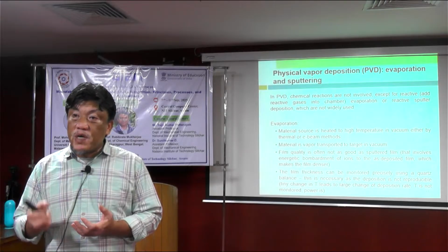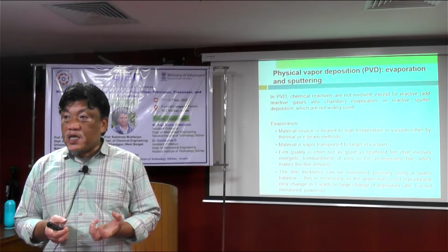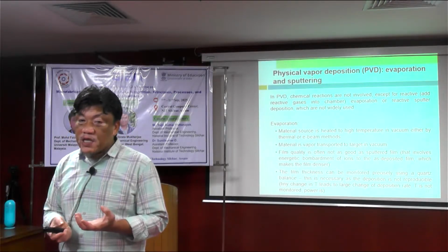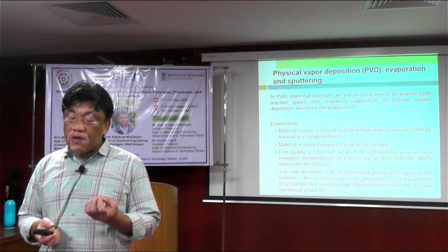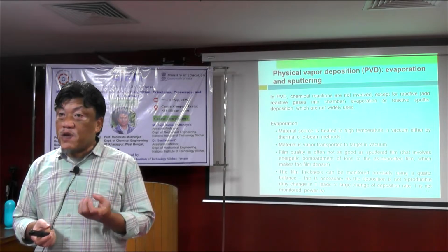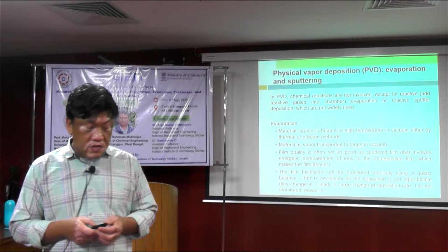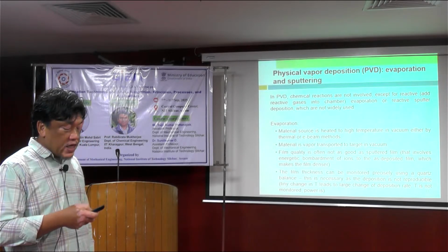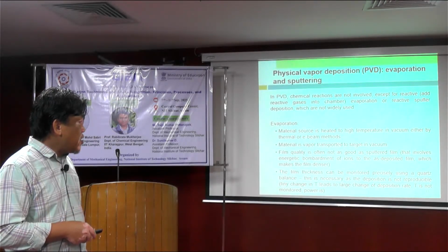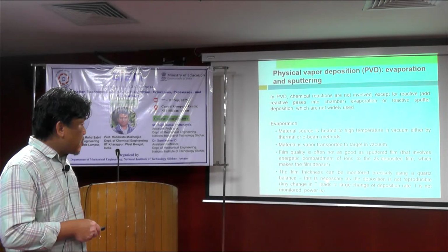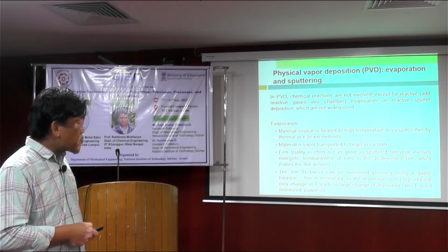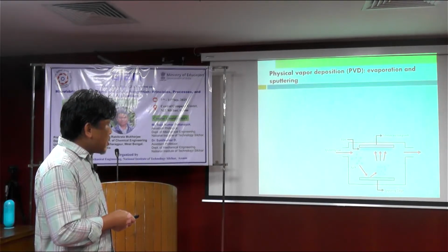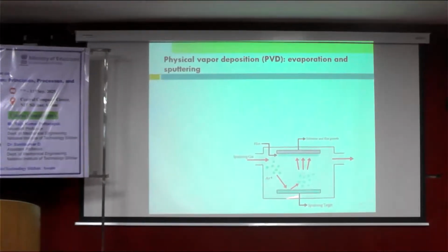So we control the power, not the temperature, whereas the temperature is the main parameter that directly controls the evaporation of the materials. So in order to monitor the thickness of the deposited material, we have to have a different way of monitoring it. So this is evaporation. This is sputtering basically.